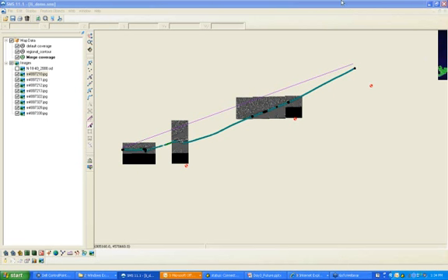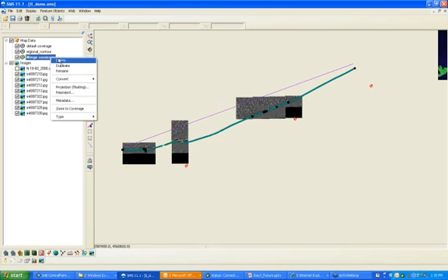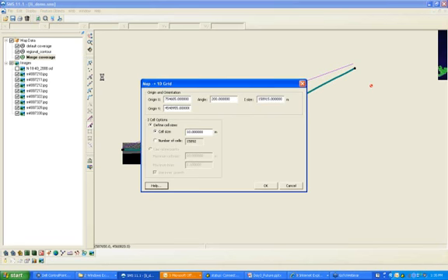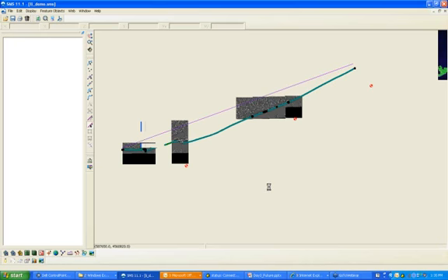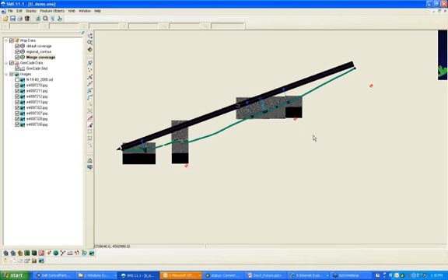All right, so we have all this set up, and I'm going to go ahead and convert this to a 1D grid before we go through and then enter any more information. So I'm going to go Merge Coverage to convert, Map to 1D Grid. And we're going to go ahead and leave everything as it is and click OK. So we'd have a very, very detailed grid in this case since we just left it at 10-meter spacing. But of course we will change that.